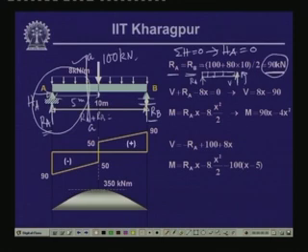So, if we take the equilibrium of the vertical forces, then V plus RA, they are in the same direction, minus 8 kilonewton per meter, and this section is at a distance of x, so minus 8 times x equals to 0. This gives us V equals 8x minus 90.